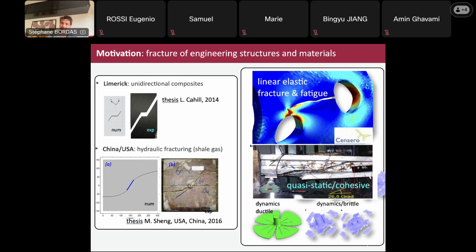And so simulating concrete in itself, even without reinforcement, is extremely tricky because of the nature of the materials. It's a material that will deform even without any load. So it will deform under its own weight. It is a multi-phase material, so essentially it flows over the years, right? So it becomes stronger, so it becomes stiffer, but it also flows, so it deforms. And that deformation is not easy to take into account, but here we're not even talking about that. We're talking about the complexity of the interface between the rebars, which are these metallic bars that you put in concrete.